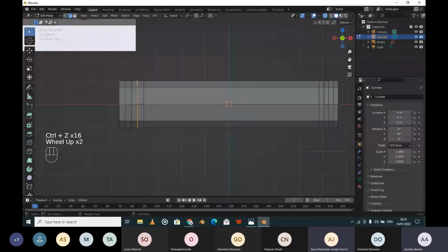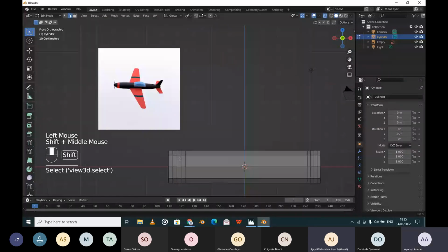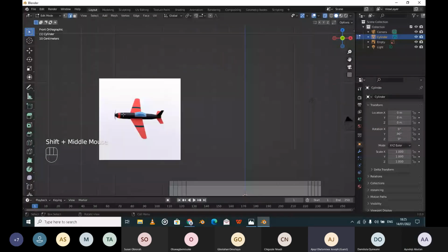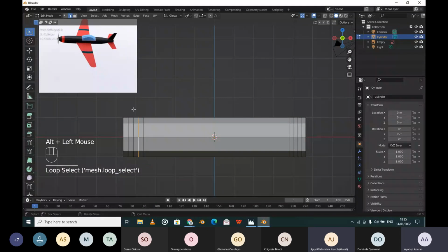When we have our loop cuts placed at the edges of the objects, at the part we want to create this shape with, what we have to do now is highlight each individual edge. You can either do that by going to X-ray mode and highlighting everything with the box select, or you can use your Alt key, Alt and select one to select everything around.